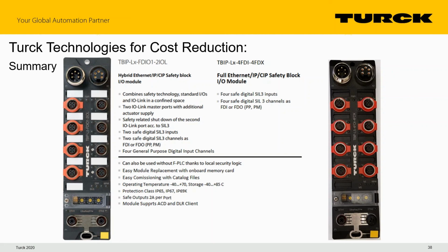The first, where they're just passing the inputs to the PLC and any outputs are being passed from the PLC back. The second use case is there is no safety PLC. There's just the logic in the safety block. And then the third is a hybrid, where you could have a safety PLC, but have local action taking place in the block.